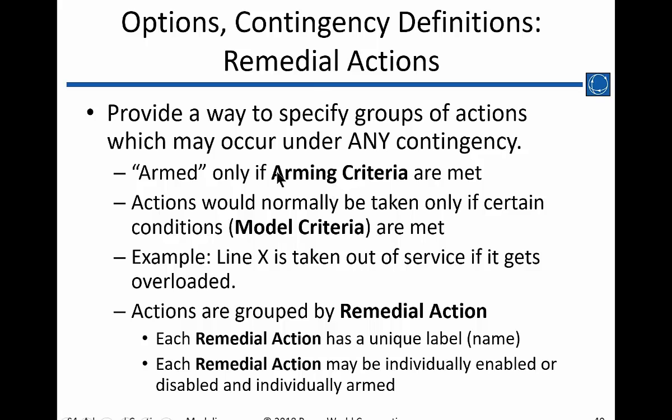An overview of remedial actions is that it's a way where you can specify groups of actions that could occur under any contingency, but only if certain conditions are met. There's a field called arming criteria, and the whole remedial action, the whole group of steps, would only possibly be eligible to occur if certain criteria is met. And then individual actions within that remedial action would be taken only if certain conditions are met.